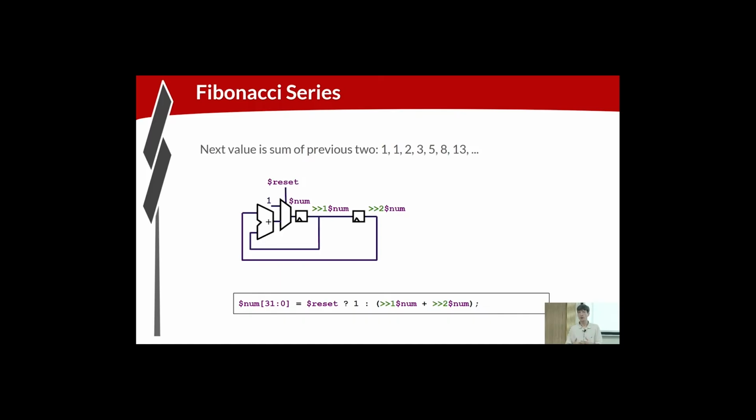So if you throw everything into the same pipeline, you could hide what's interesting, that there's stuff happening between operations that are conceptually independent. So for the choice of what logic goes into what pipeline, TL-Verilog is not forcing you into any mode of design, but just naturally partitioning the logic results in natural looking code. And that organization into pipelines helps to frame the way you look at the logic and think about the logic.